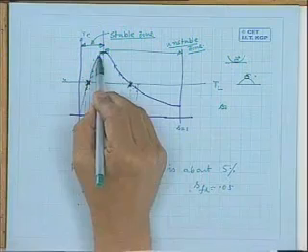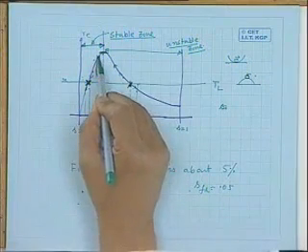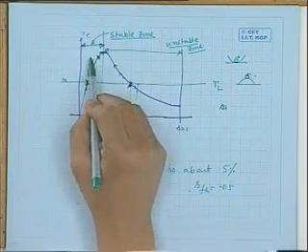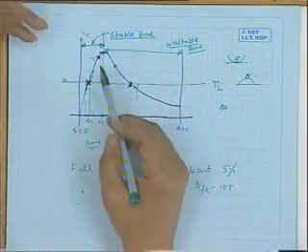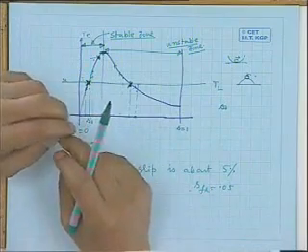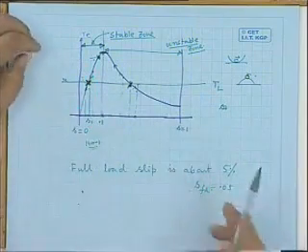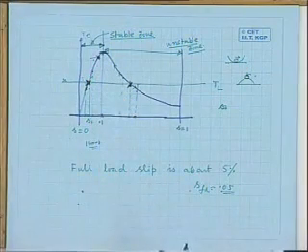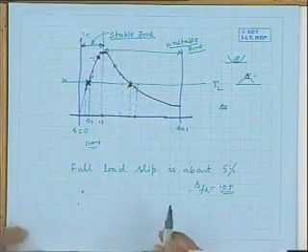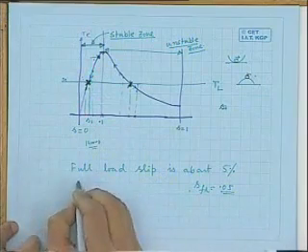Generally, the full load slip is designed so that the machine will not be going to that. If you design an induction motor perhaps with a slip of, say, 0.09, very close to that, at full load operation a slight disturbance may bring the machine to this side and will give you wrong operation. Therefore, this point is to be understood.